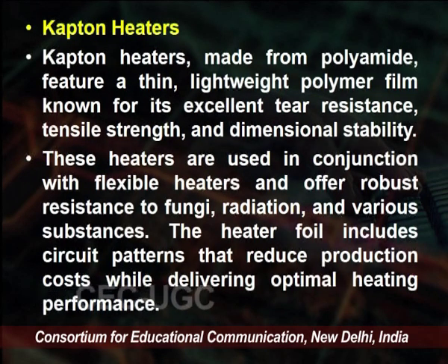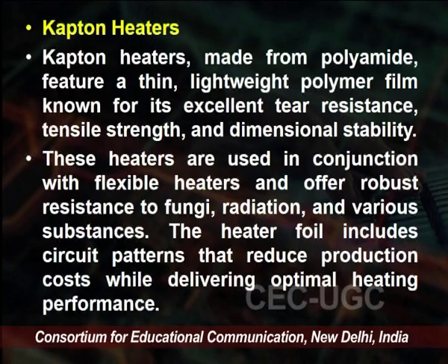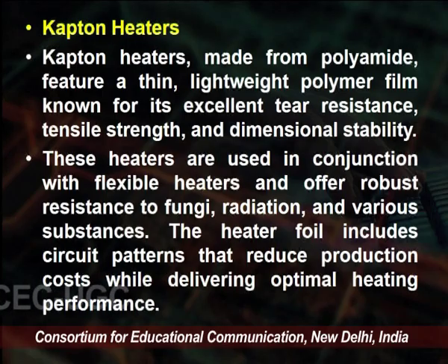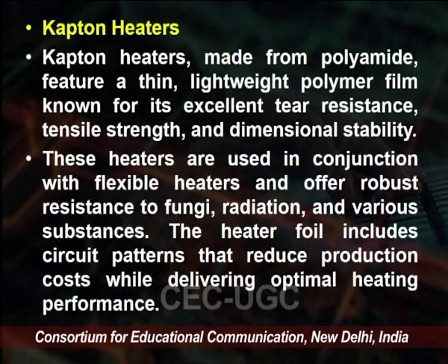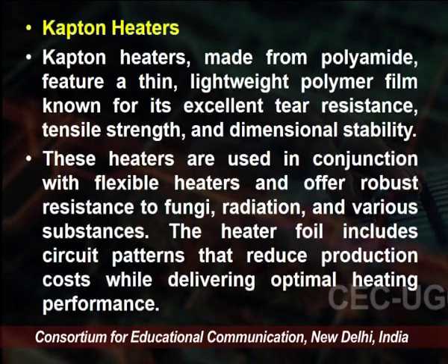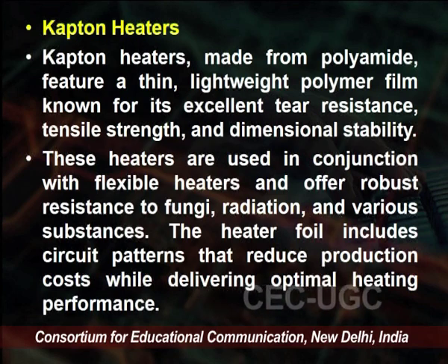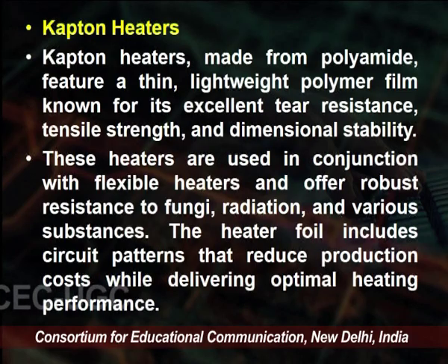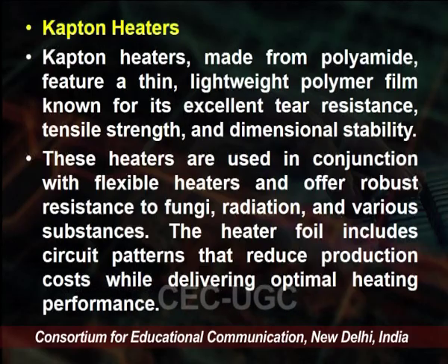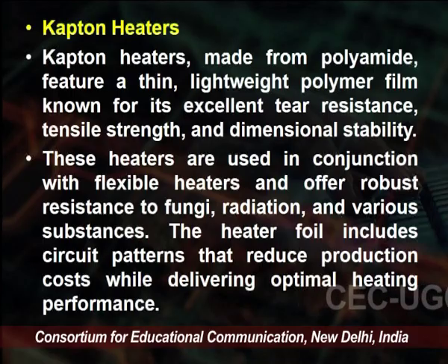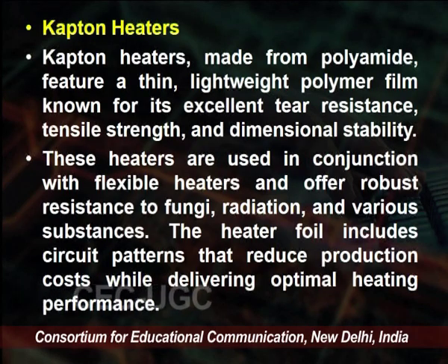Another important type of heater is the Kapton heater. These Kapton heaters are made from polyimide, a thin lightweight polymer film known for its excellent tear resistance, tensile strength and dimensional stability. So these are flexible heaters and offer robust resistance to radiation and various substances. The heater foil includes circuit patterns that reduce the production cost while delivering optimal heating performance.